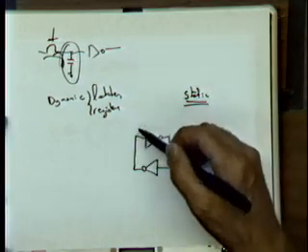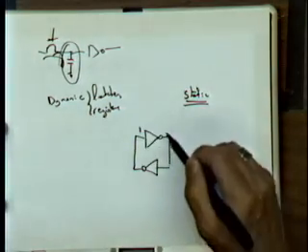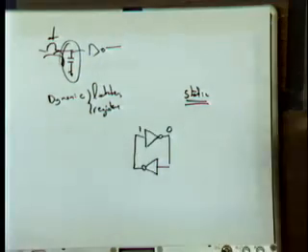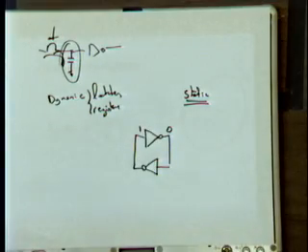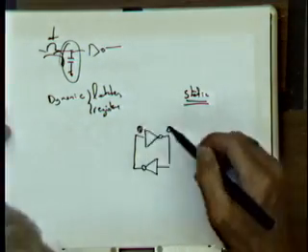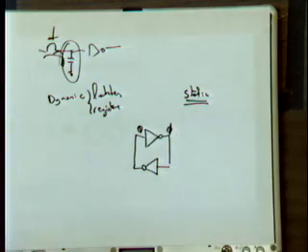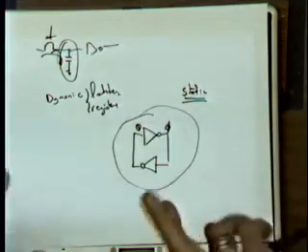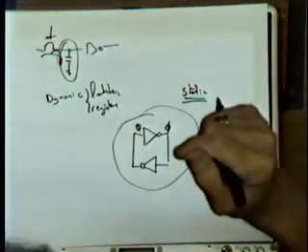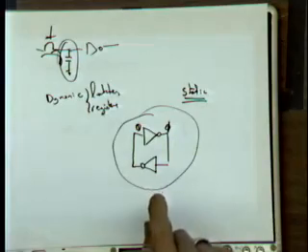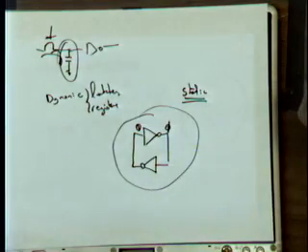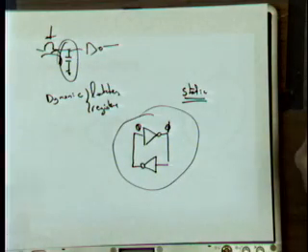For instance, if I put a 1 here, this is going to be a 0, this is going to be a 1, and it remembers the same thing. Similarly, I can have a 0 here and a 1 here. So a cross-coupling of two inverters becomes a memory element. If I don't remove the supply voltage, it will remember it forever. Obviously, when I remove the supply voltage, it will go away, so you might need other memories that remember things even without supply voltage, but that's another topic.